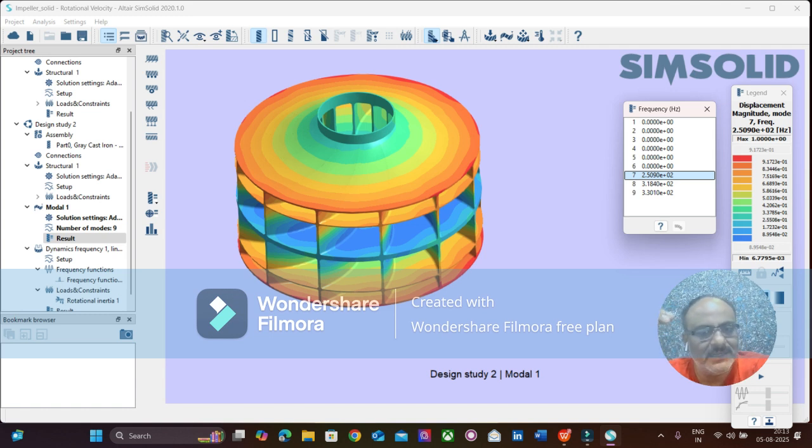So that yielded a certain deformation and a stress. The deformation was about 0.045 m, and the stress value was about 41 N/mm². And we said that the structure seems to be stable and safe. However, just because these structures experienced a lot of vibration, we decided to go for modal dynamics. We performed a normal mode simulation, extracted the three frequencies, and now we are going to get into frequency responses.